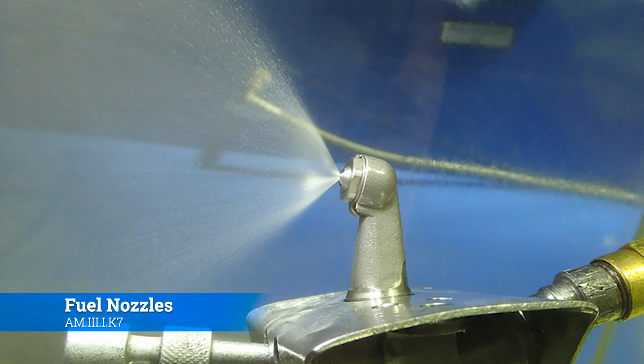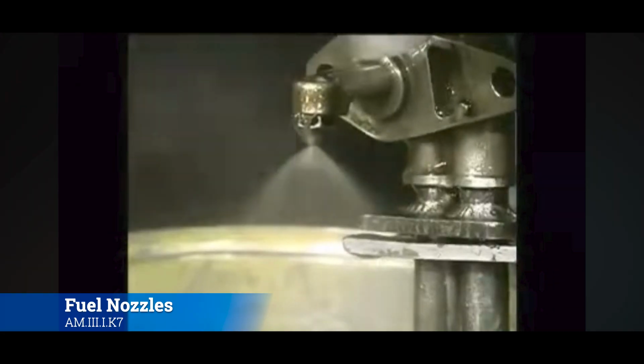And the simplex nozzle does it very, very simply. It's just like a spray bottle. There's no crazy dynamics going on inside of the nozzle to create two different flows and two different bodies of fuel or anything like that. This is really just a nozzle that sprays it out. Pretty simple. Alright, this is the PT6 fuel nozzle.